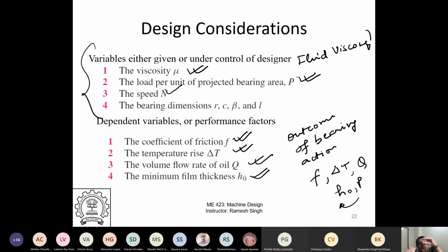And there will be a supporting film thickness. So there will be film thickness which will physically separate the shaft and the sleeve, and there will be pressure generation. So this pressure which you're talking about is just load per unit area, but there will also be pressure in the film. That is a dependent variable. This film pressure, which evolves, is also a dependent variable.